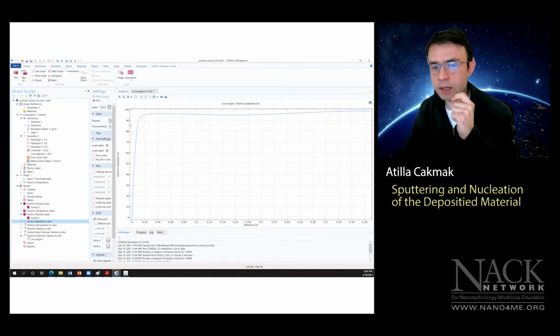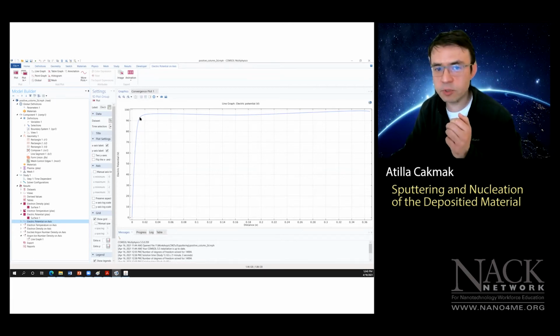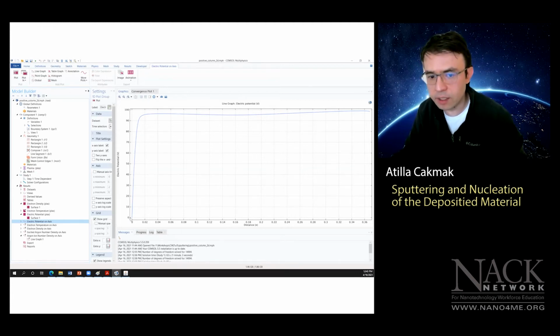So we're going to place the target here, and this is going to be like a roller coaster. Once the ion is generated inside the plasma, the electron will generate the ion. The ion will come down and literally ride a little roller coaster in here. It's going to be like, ooh, coming down and attacking the target area, because this voltage difference will give the ion enough energy to attack the target side, to knock off the target atoms from within the plasma chamber, within the sputtering chamber, okay?